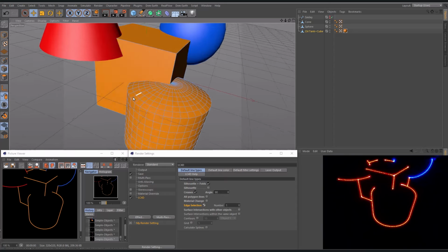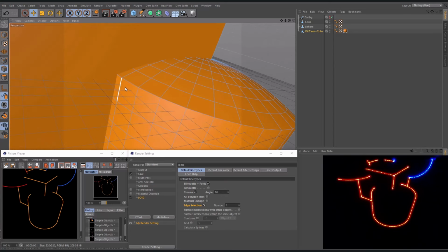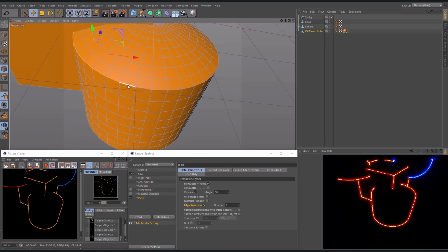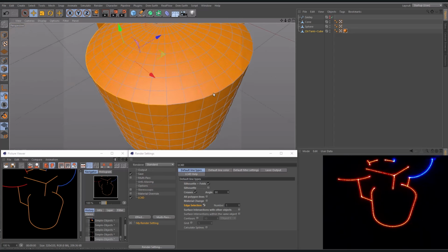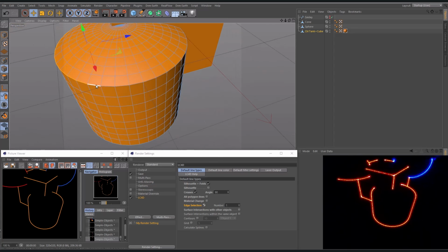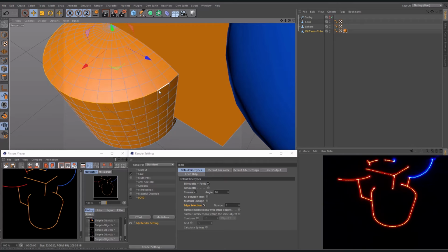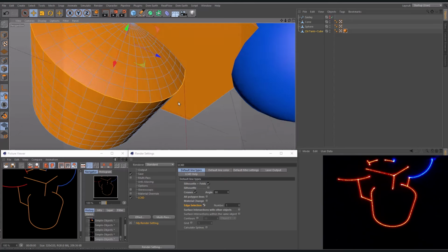To show this, I will now create 2 separate edge selections. First selection should be the outer edge of this tank-shaped object. So simply select the whole outer shape or edge of this object by holding down the Shift key and using the marker tool. As a small hint, by the way, for some objects, especially for example spheres or cones, the selection of surface lines fully surrounding the object can be simply selected by double-clicking. This is not possible here since the contour line is interrupted by the collision with the center cube object.